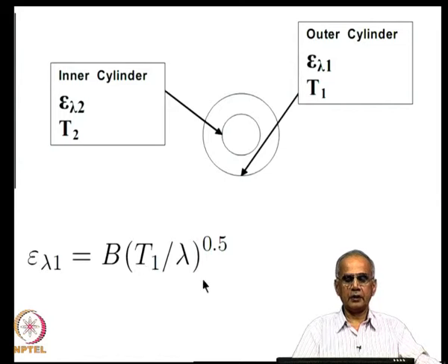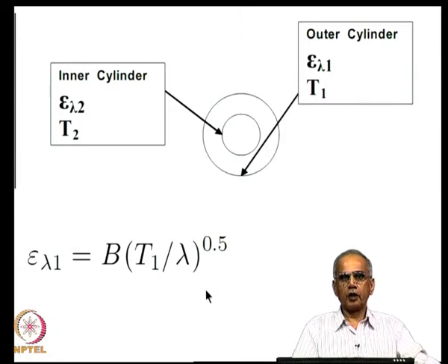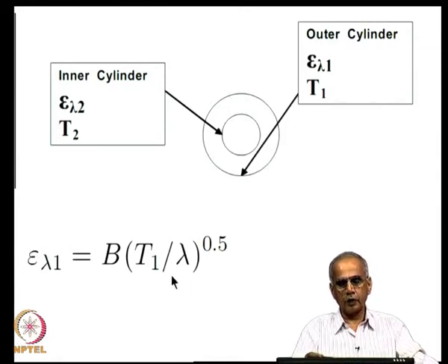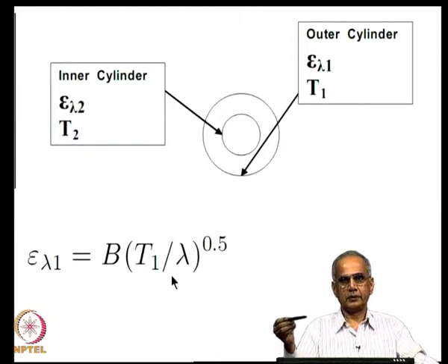What really happens is that the Debye flask containing hydrogen, being at a lower temperature, absorbs about half the radiation compared to the Debye flask containing liquid nitrogen, mainly because emissivity decreases with temperature. That is the main effect. But if you really want to account for all other phenomena occurring there, including changes in how the emissivity varies, you get this 60% change.